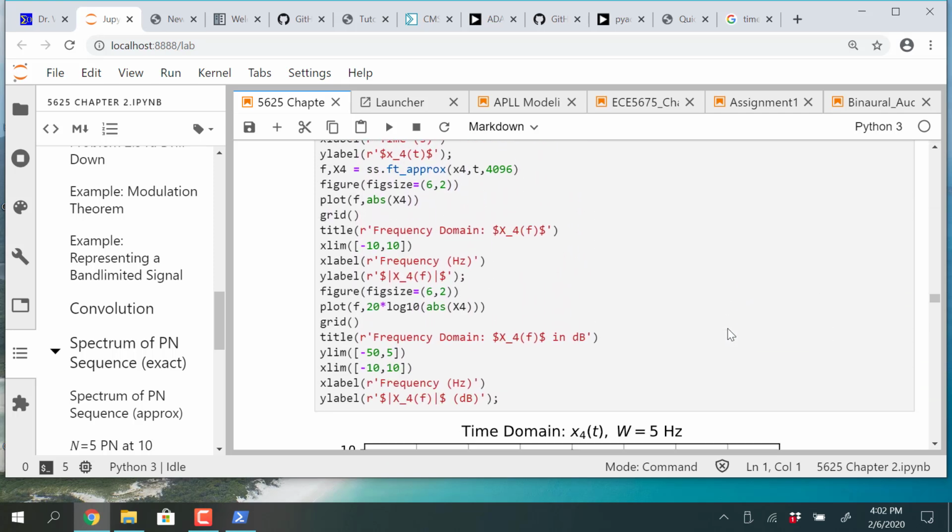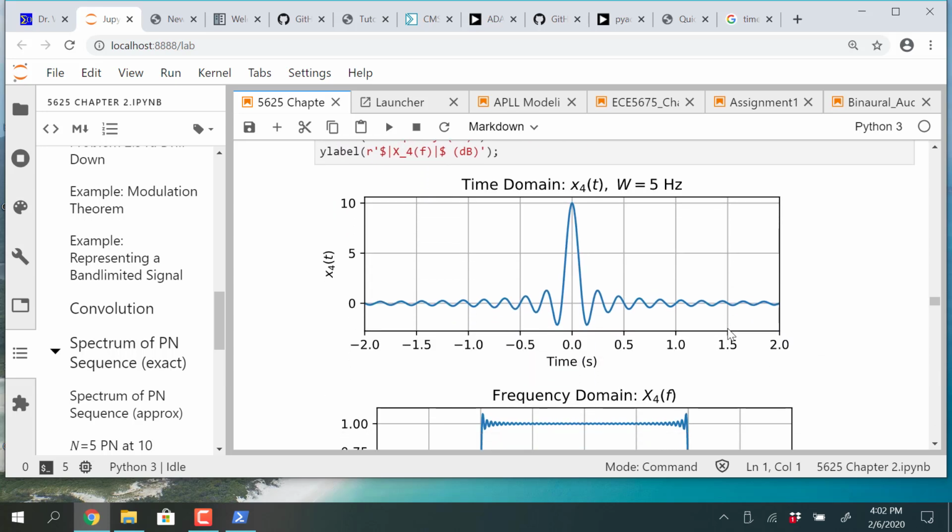Question? Yeah, so let me see here, I think. So you put a Gaussian time function on top of that, that would reduce it, right? Yeah, the side lobes. You'd put a window on there and that would reduce it. Okay. And a Gaussian is pretty smooth. A Gaussian has the property though that the transform of a Gaussian is another Gaussian. So that's a very special signal.